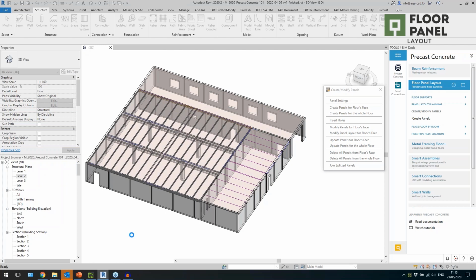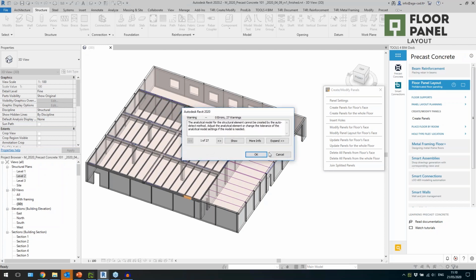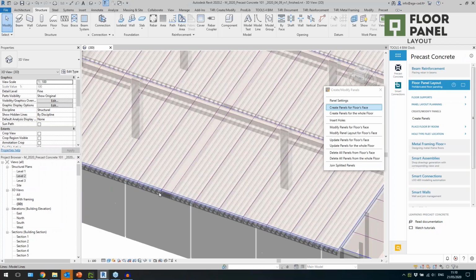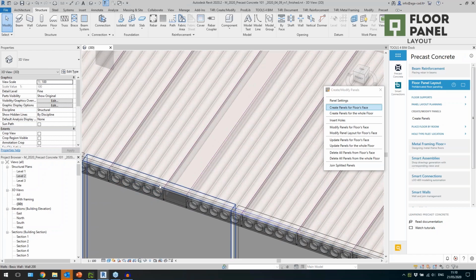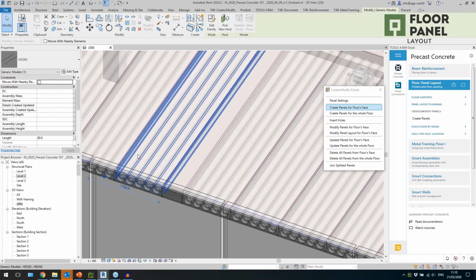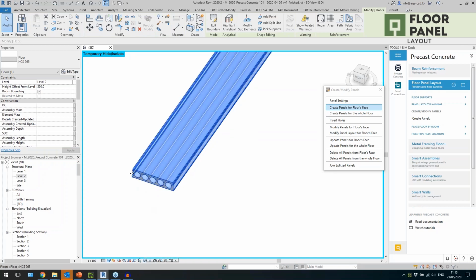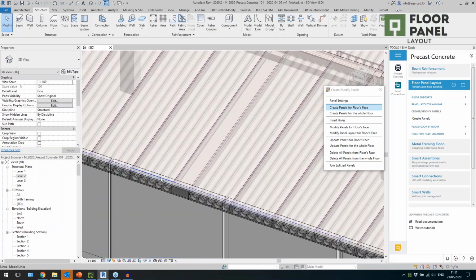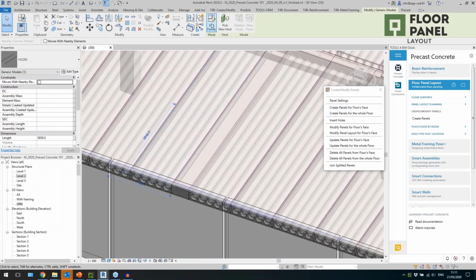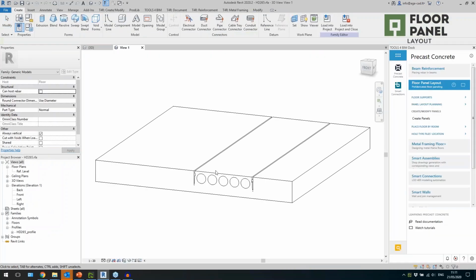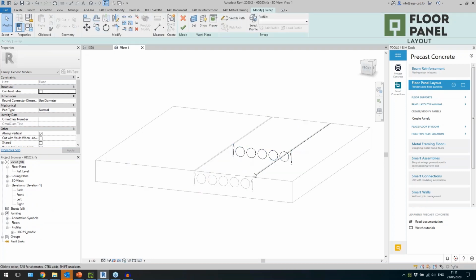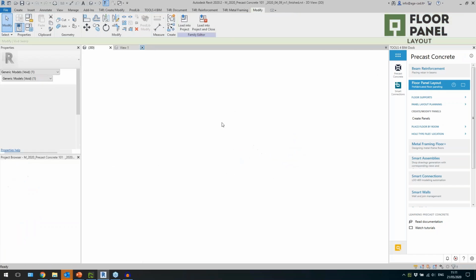Some analytical model was disrupted in some areas. Not a problem here, but oh, so I created slab over here as well. So I should have maybe used that only for the floor face. But now what I have here is my hollow core slabs with some cutout. This cutout, it could be a different family. For example, if I select that, you will see that this is sweep shape. You can define what should be, just draw the lines and define what should be the shape of the slab.